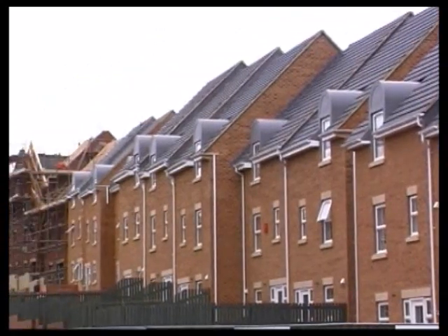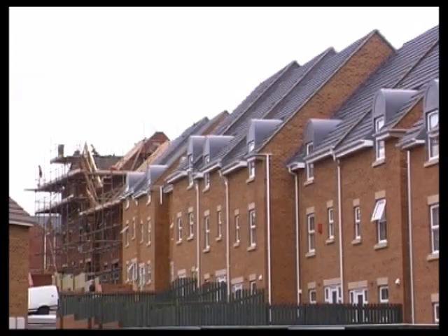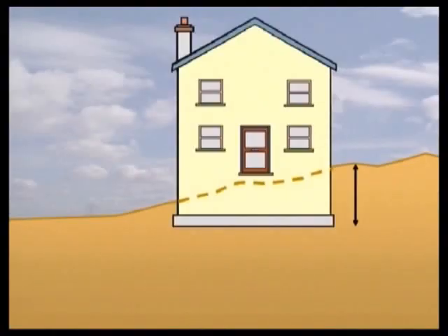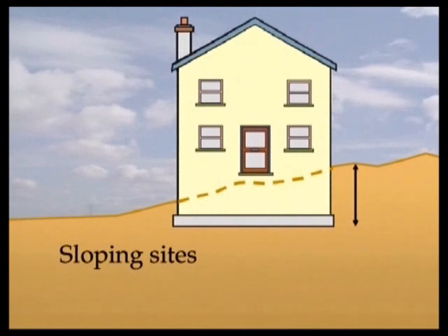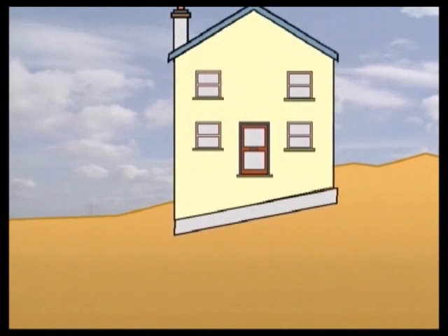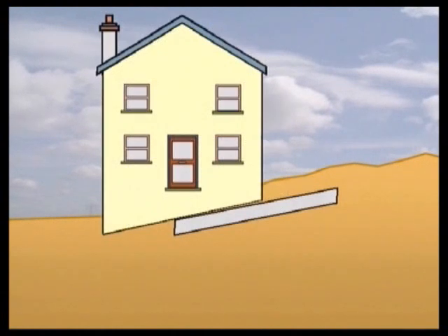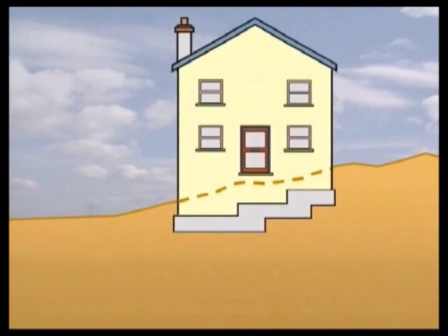Foundations have to be laid level, and on sloping sites, this can lead to a lot of excavation and expensive earthwork support. Trying to slope the foundation to match the fall of the ground is obviously not an option. To keep the excavation to a minimum and to ensure a level surface for the building, the foundation can be stepped.